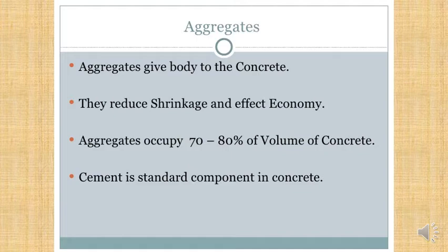Cement does the same thing. It holds the strong components together so that they work together. It holds the aggregate particles together so it forms a strong material. And concrete is very strong, particularly in compressive strength. Now, that's important. So when concrete breaks, when it cracks, it very rarely breaks through the aggregate. It actually breaks through the cement.